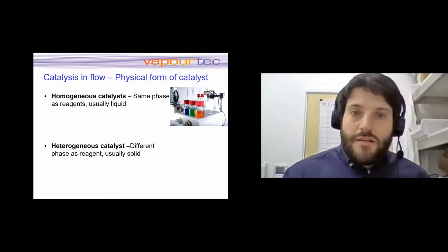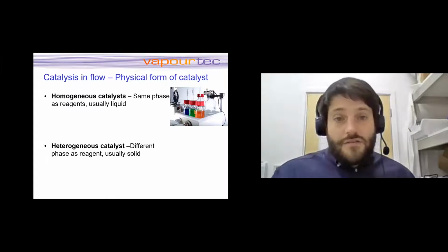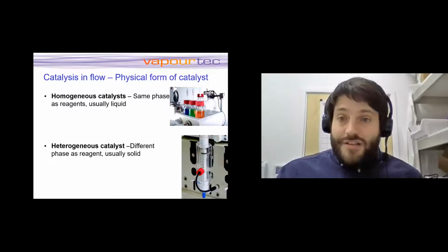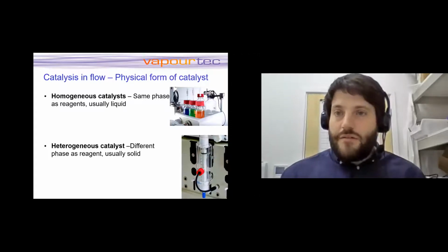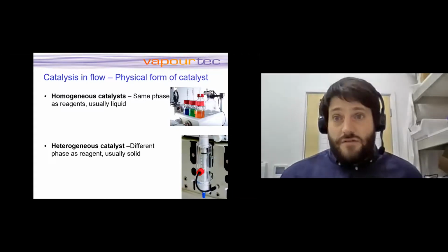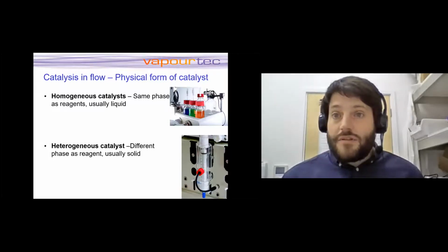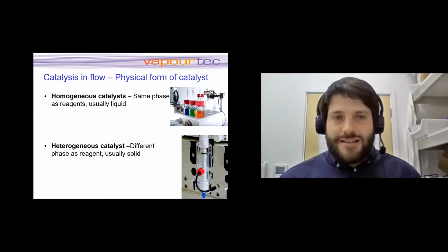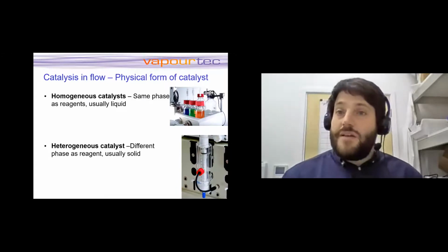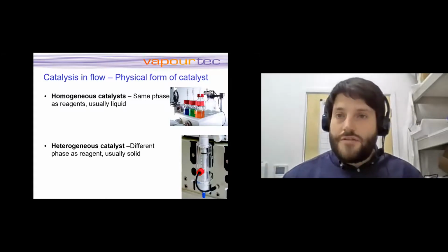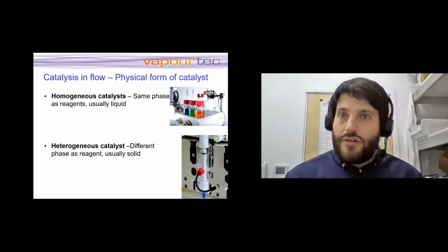If we are looking at the solid phase, heterogeneous catalysts, there are different phases of our liquid reagents. Traditionally, people have packed them in a fixed bed column because it's very simple, it's very effective, and that's a really easy way to deal with solids. Flow chemistry is usually not good with solids, but this has changed in the last years through some products we developed. But this is effectively like an HPLC column. We will have our solid packed in a column and our reagents will flow through. So this is how we'll have a contact of solid liquid phase.